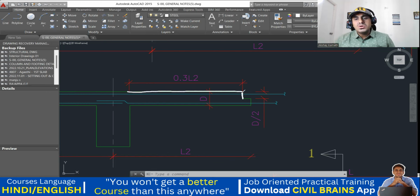Okay, and then you have to stop it like this, always for the slab. For the beam, it was something like this, no? Why is it like this here? For the slab, see, for the beam it was something like this, isn't it? Why for the slab is it only like this? Because slab depth is how much? Slab thickness is hardly 150. Beam was like 450, 600.